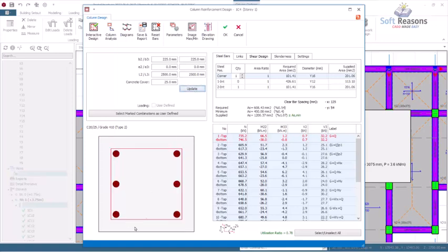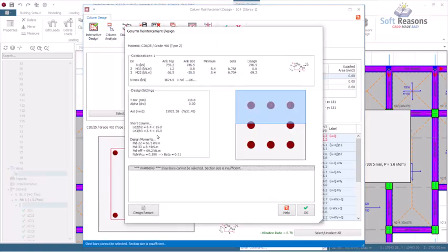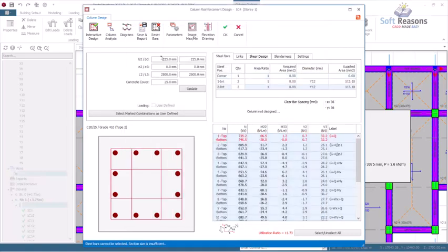Click on the update option, so you have this. You can reset bars in these provisions to at first have 4 bars, and then you can click on interactive design, which will now have this, and you can see a warning right there. Still bars cannot be selected because the section is not sufficient. We are using a very low section, so you have to now increase it.